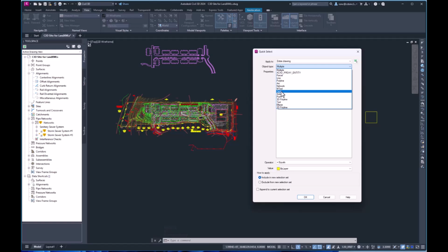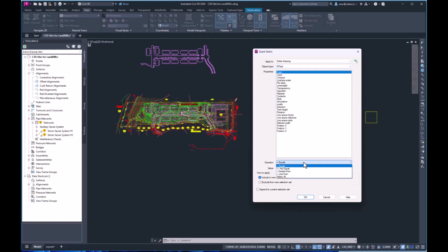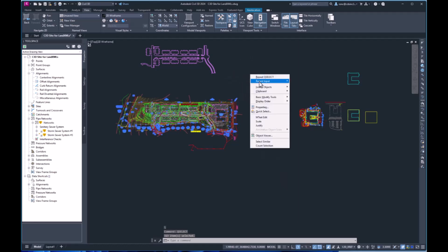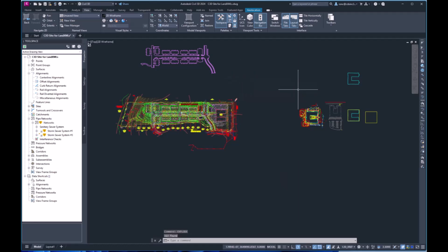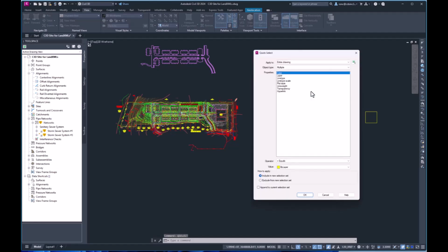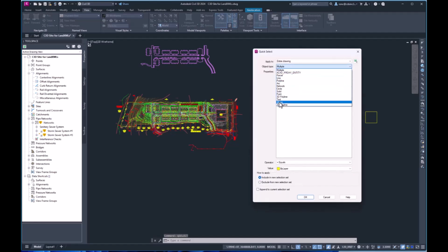Now, I don't like multiple text, and I've got my own reason for it. So normally I will select all the MText. That's one piece of text, but it's multi-lines of text. And I'm going to select all. And there's 323 of them. And I'm going to explode them down to single lines of text. So we are good through here.